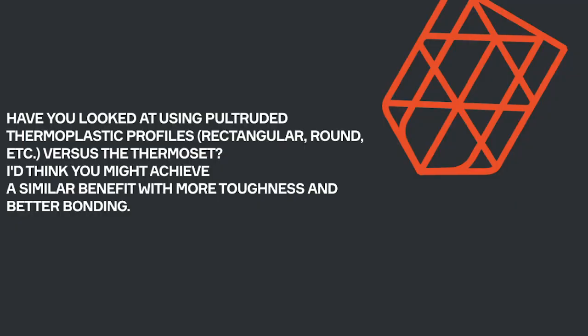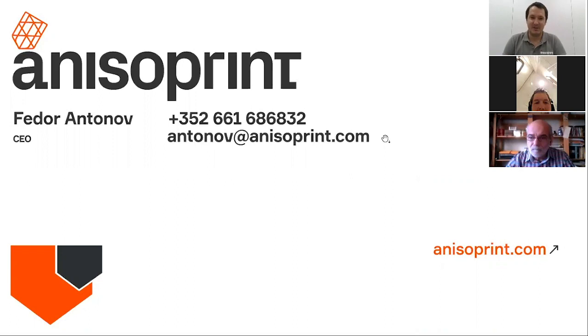Have you looked at using pultruded thermoplastic profiles versus the thermoset? I think you might achieve a similar benefit with more toughness and better bonding. Of course, that's a very good comment. And yes, we are also looking into that. It has certain benefits versus thermosets, you're right. It has certain drawbacks as well. But yes, we also have such materials in our R&D being tested, and maybe we will also offer it, especially for the high temperature solution.